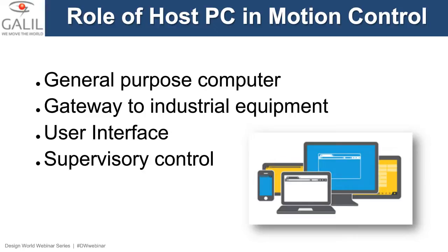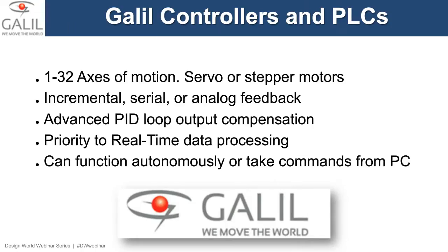But what they lack is really a specialty to perform motion control. This is really where the Galil controllers and PLCs can come in your system. For Galil controllers and PLCs, we're talking about controlling a position, velocity, acceleration of your various motors, of your various actuators in your system. You take in a variety of feedback, whether it's different encoder types or different signals.